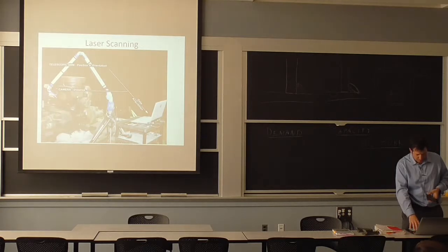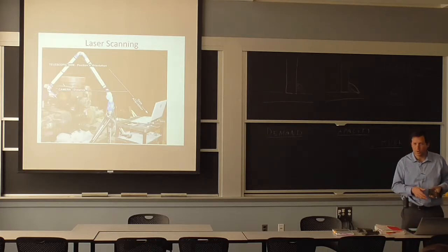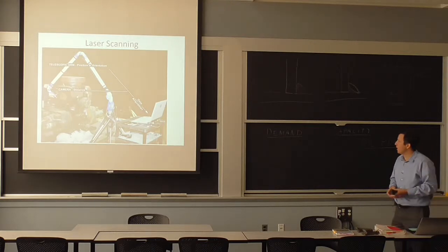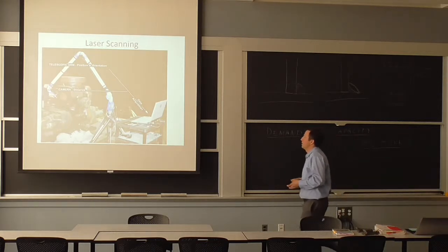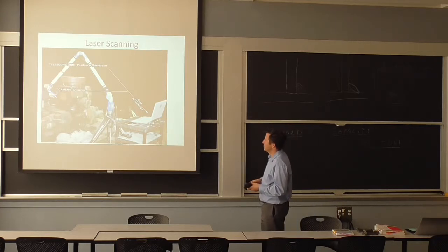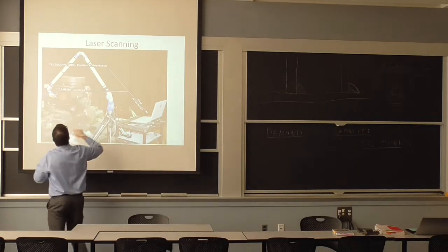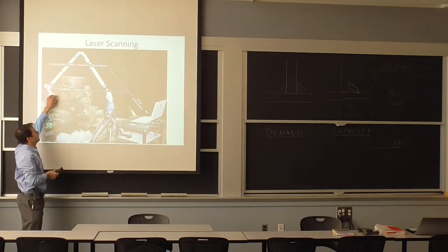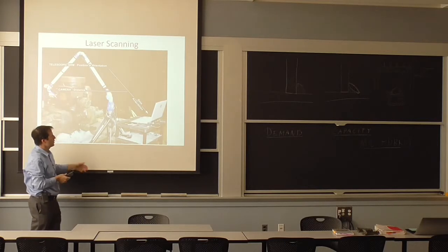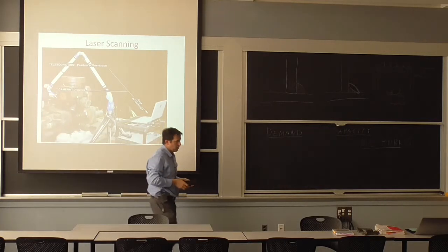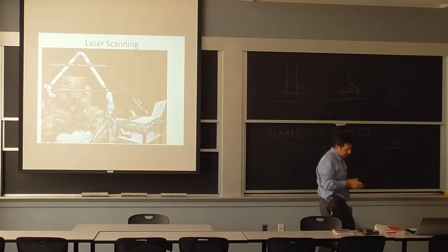Something that is typical, not just for aerospace, but for reverse engineering, is to get the dimensions. Here, just showing a typical laser scanning system, and we're doing it on a blowout parameter, so it's not this type of component, but essentially you have a multi-axis system, and the head here is a laser that multi-focuses and gets you the exact profile of the surface at very high resolution.